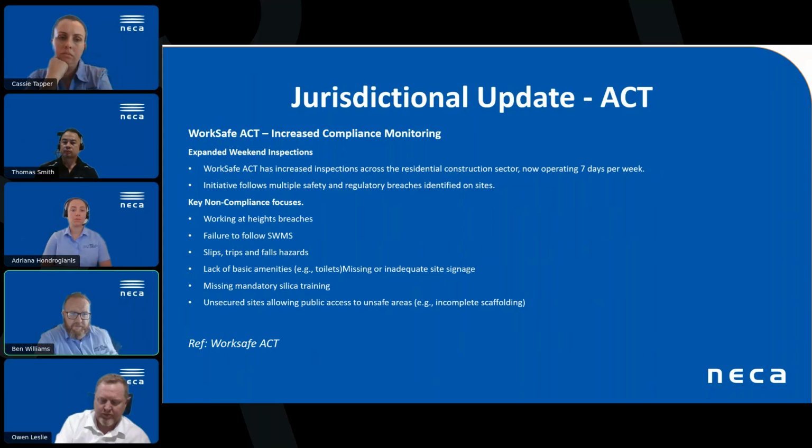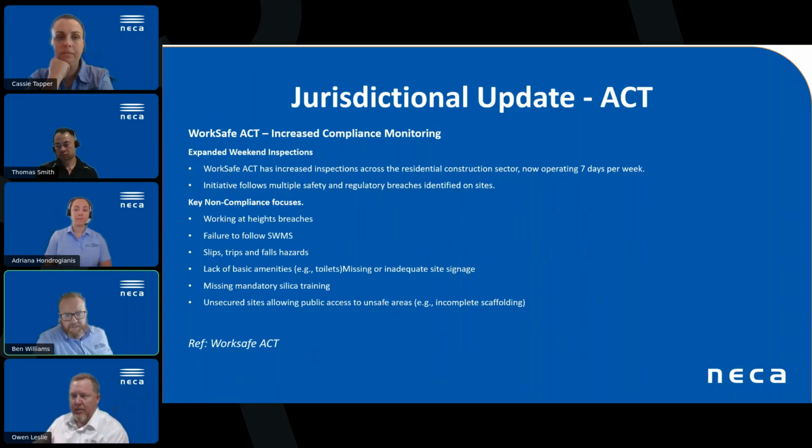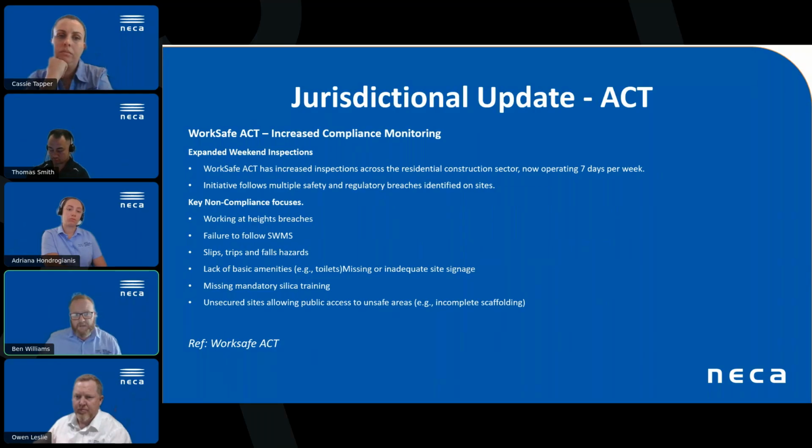And the key focus of these inspections will be working at heights, failure to follow SWMS, slips, trips and falls, the lack of basic amenities within these sites, so toilets, signage, those sorts of things, and obviously the missing silica training, which is mandatory across the ACT. Having those unsecure sites and allowing public access across the ACT's residential construction sector has been a big issue for a while. So just making sure those ones are under control, that's always best to be on the front foot with that one.